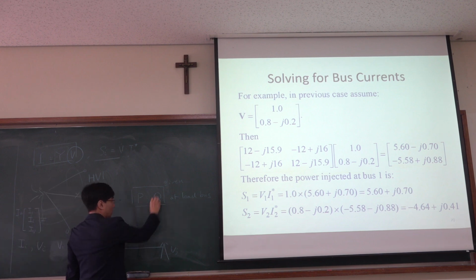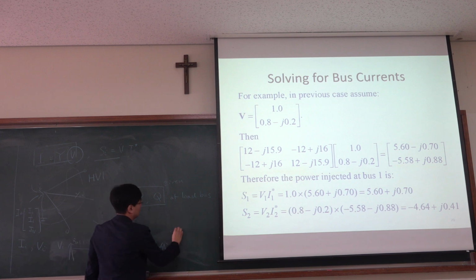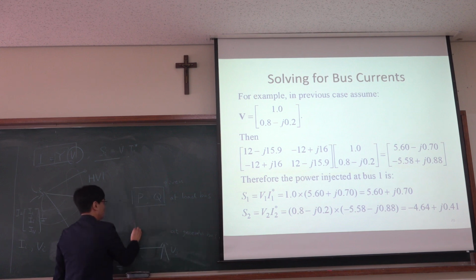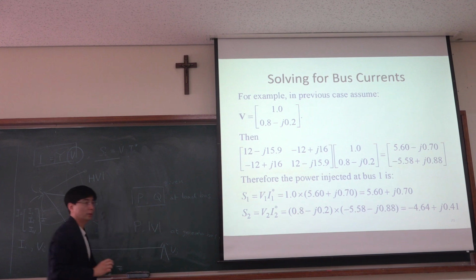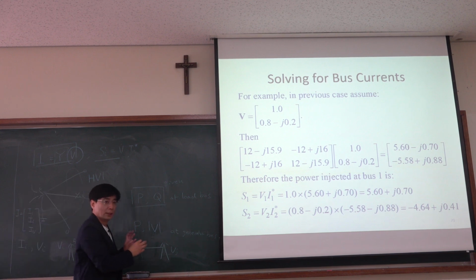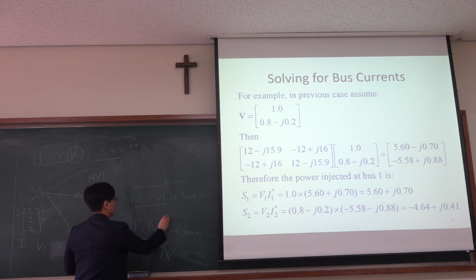Also, we assume that at the generator bus, the active power injection and the voltage magnitude are given. This is just set by the power plant operator.